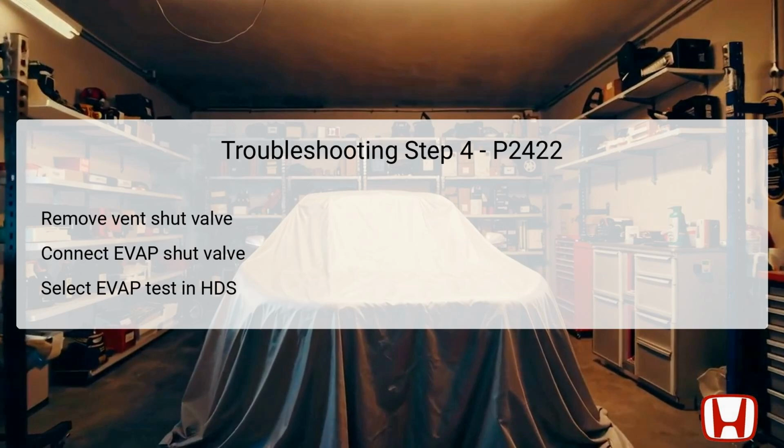Pay close attention to whether the valve operates freely without corrosion or corrosion-induced hindrances that can affect performance. Evaluating this component accurately is vital, as its failure directly contributes to the malfunction described by DTC P2422. If it operates correctly, you can proceed to additional testing steps to further diagnose the issue.